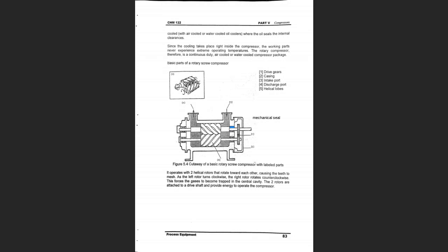As the shaft rotates, this mechanical sealing, guys, will get damaged over time. That's why you need to check it every certain period of time and replace it if needed. The mechanical seal prevents leakage from inside the pump to the outside, and you have to check it periodically to make sure it has not worn down due to friction, and replace it from time to time.